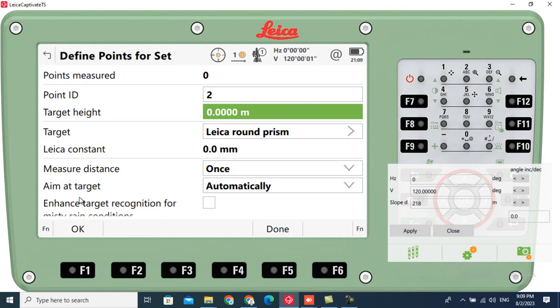It just goes by the angle. You said the auto aiming total station centers on mini prism, normal prism and 360 prisms, but for sheet prism and reflectorless it doesn't center.